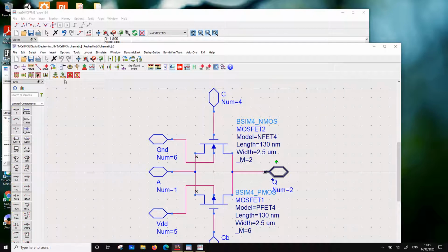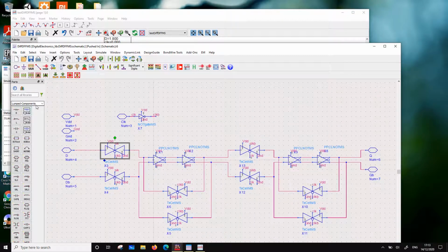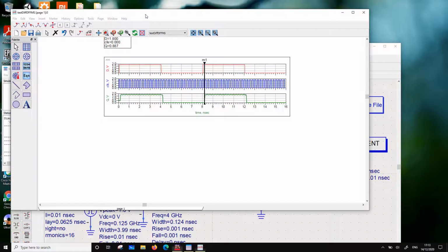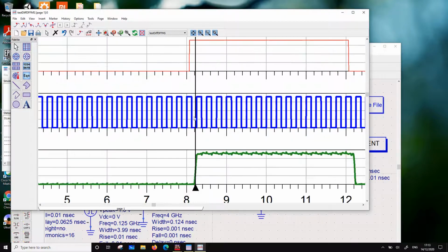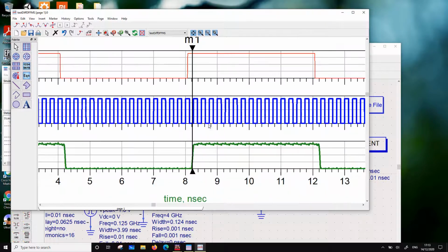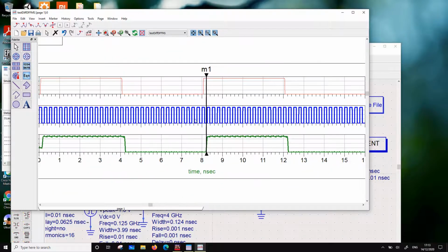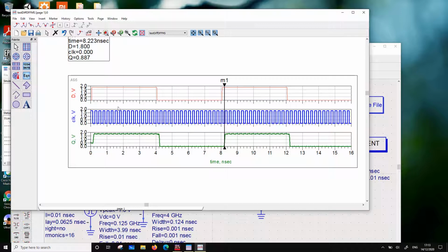So what I have just demonstrated to you is it cannot be used at 4 gigahertz, though I'm simulating it, because you should have a certain setup time before the positive edge. If I have a transition at the positive edge, that means that this circuit will fail in the larger circuit if you use that at 4 gigahertz. Anyways, so these delays, what they mean to you.